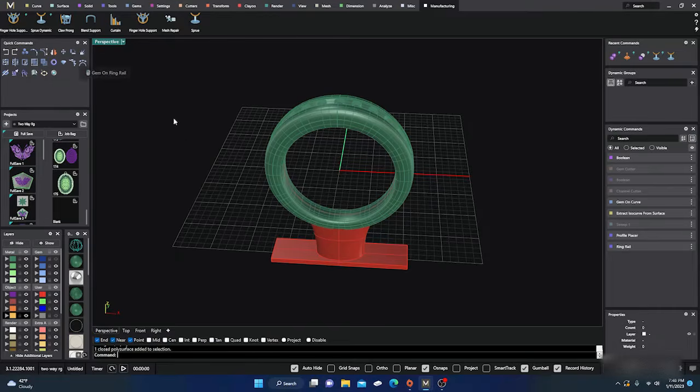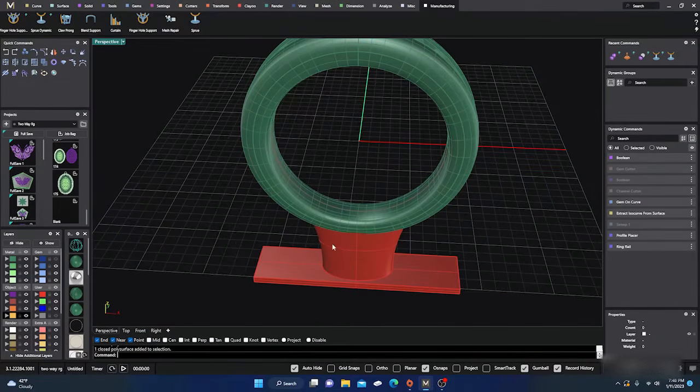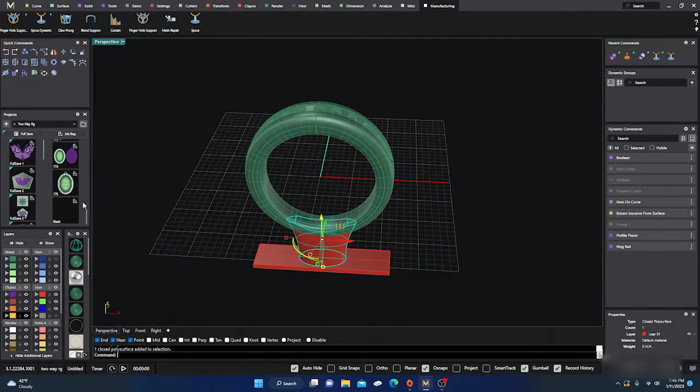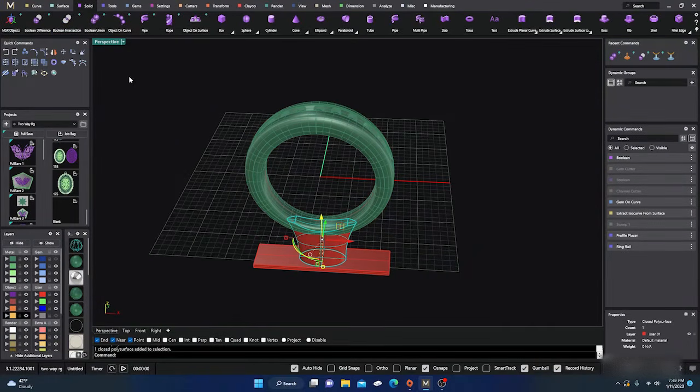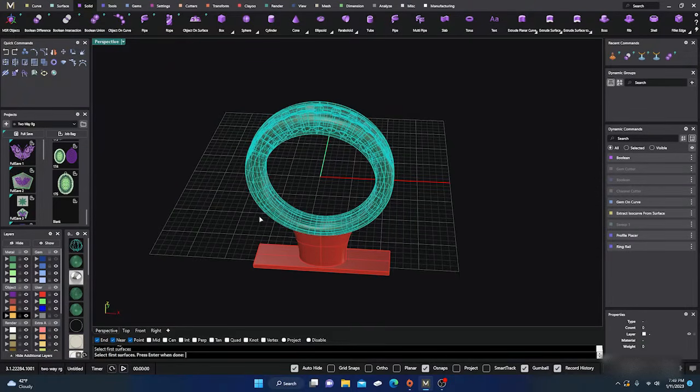But you can join things together. So say I want to just make all this. Right now I have 3 pieces out here, right? Again, right now you should probably job bag it. So I would go into my tools and do Boolean union this time, because I want to join these surfaces together. So I take a Boolean union, select my first surface, select my second surface, hit enter,